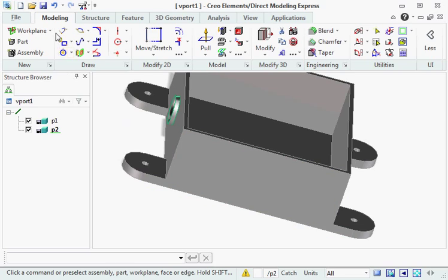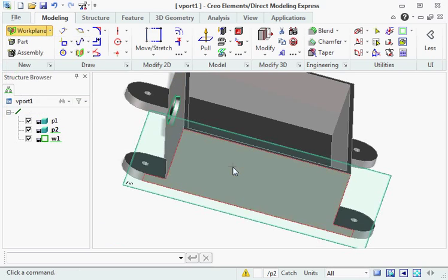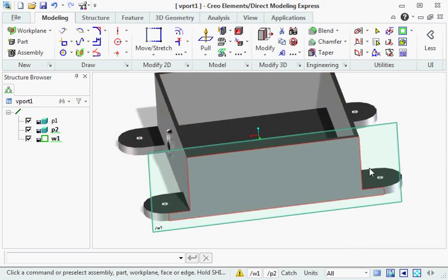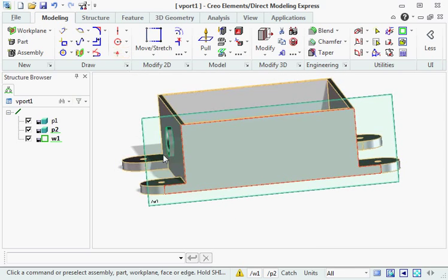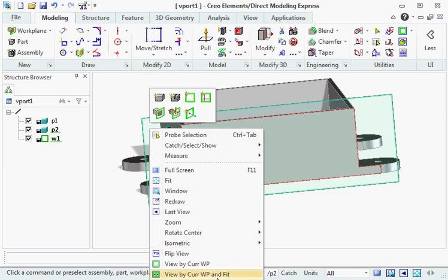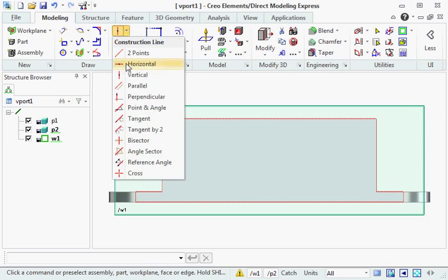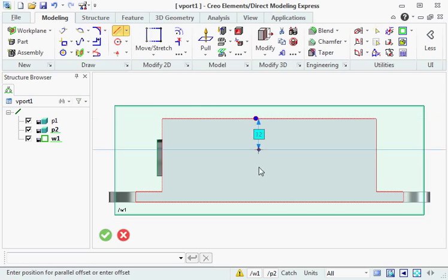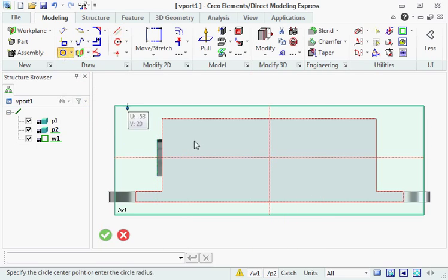One of my favorite features is auxiliary geometry, where I can draw thin lines with specific distances, at a specific angle, or in the center of existing geometry. Then I use this thin line as a guide for the geometry used for modification. For instance, here we find the center of this box's wall, so we can put this circle in the middle of this wall, and then we can make the hole in this object when we select it as active.